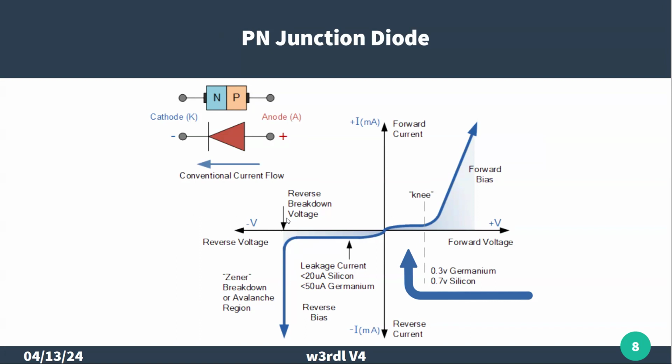We take advantage of that in making what we call Zener diodes, where you operate them in reverse potential, and they can manufacture the diode so this Zener or breakdown voltage is very precise. They can make one at 10 volts or 10.2 volts, and we use those as voltage sources, reference sources.